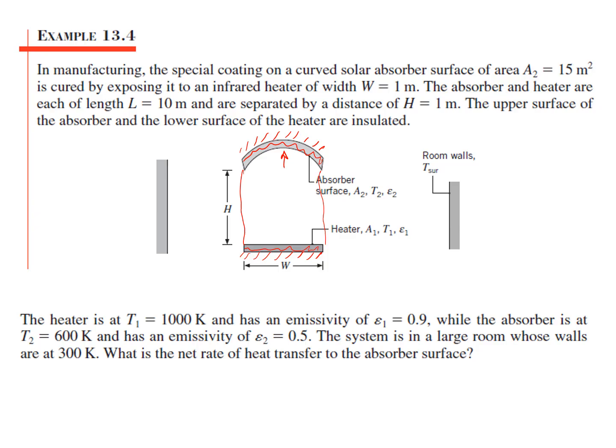Those two surfaces on the sides, I can just consider them like imaginary surfaces, call them the surrounding surfaces, and assume that they're like black bodies, because any radiation towards them is not going to be reflected back. But they are at a very low temperature, 300 kelvins, so they do receive some net radiation, or in other words, they do emit radiation at 300 kelvins.